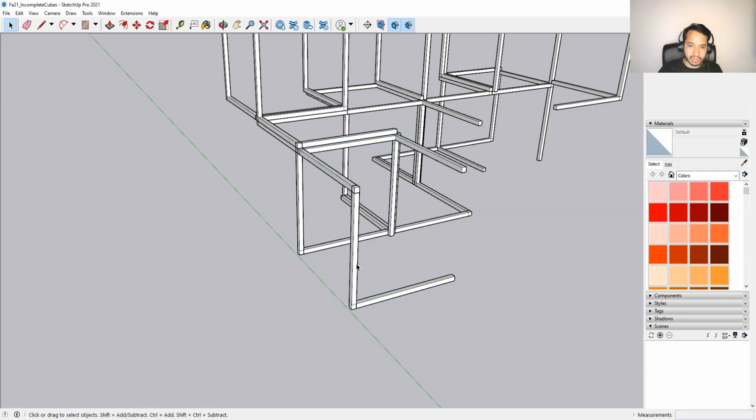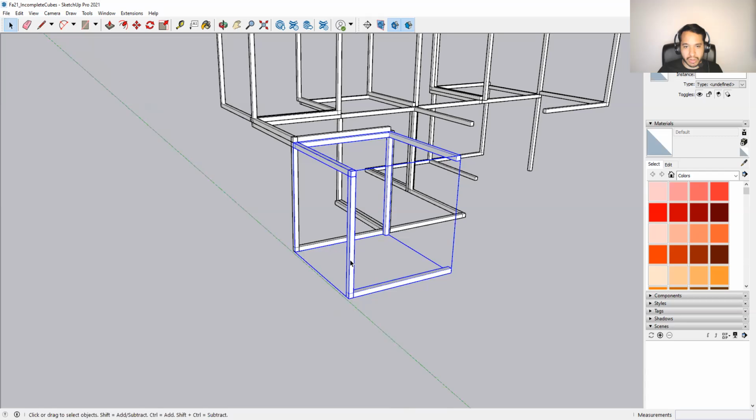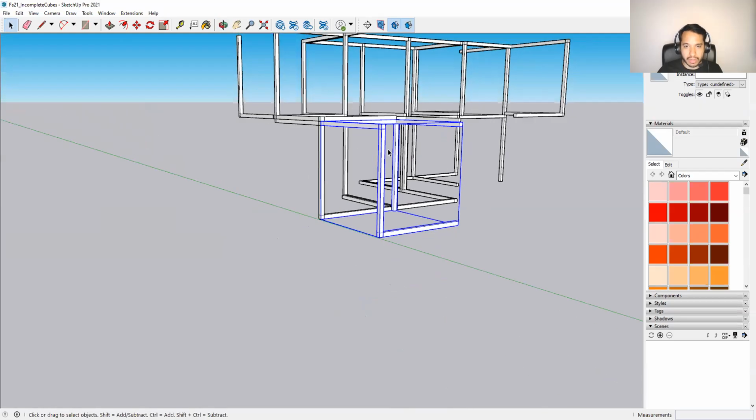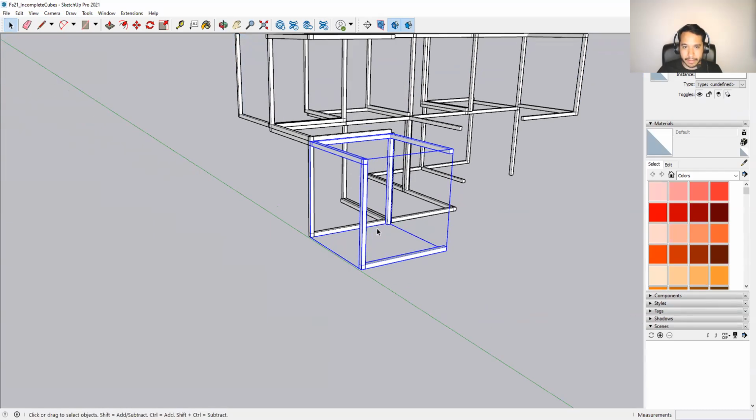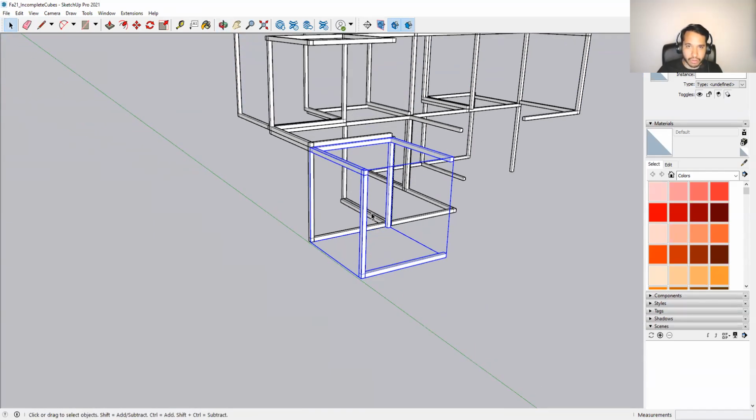Now, when we're calculating square footage, we're not calculating what we call the z-axis or the three-dimensional axis. It's simply just the floor space. Okay. We're not calculating volume, which would then require us to do 12 times 12 times 12. That's what we're not doing. What we are doing is just multiplying 12 times 12. That gives us the usable floor space, the usable square footage.